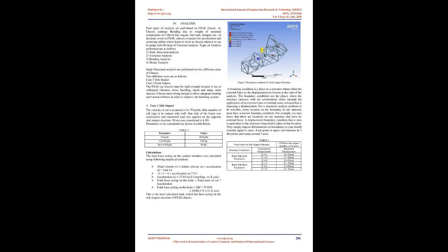While modeling the stiffness contribution from each part of the frame, the method used to apply the loads and constrain the frame plays a significant role for an accurate analysis. Accurate analysis means predicting the stiffness of the frame close to the actual stiffness as the frame operates in real conditions. The problem here has normally been how to constrain and load a frame, so as to receive multiple load inputs from a suspension while it has been separated from that suspension, and many other such problems.